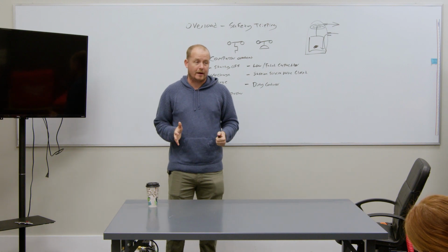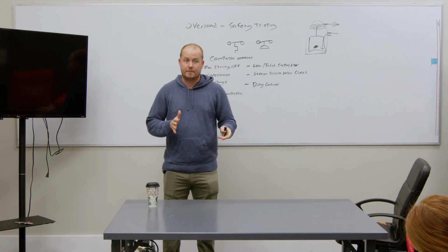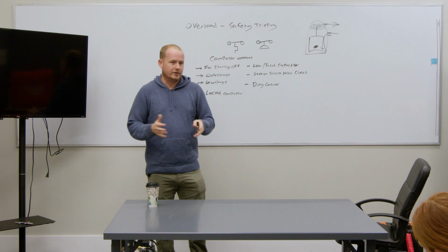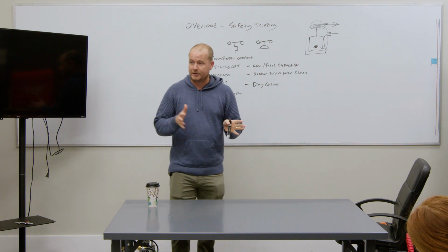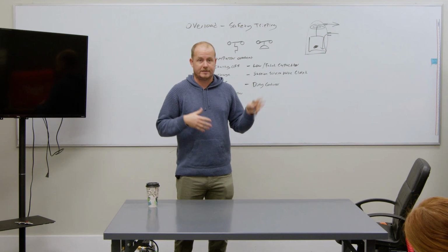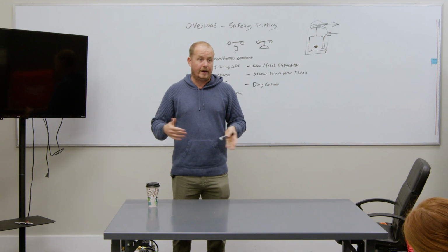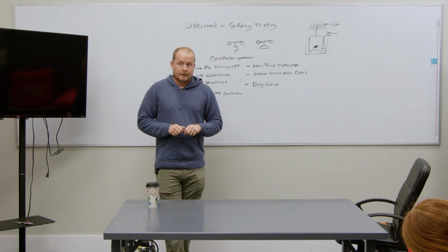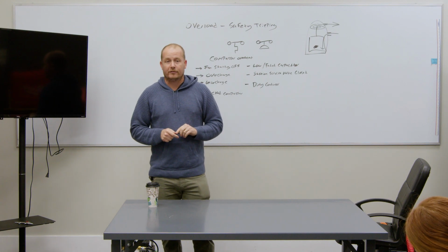So you've got a compressor going on thermal overload. What's going to happen? It's going to be shutting off. If it's locked, it's going to be trying to start and shutting off. If it's running, but it's just overheating because of some of these conditions during running, it's going to run for a while and then it's going to shut off, and then you're going to have to cool it down before it starts again. What is our suggested method of cooling a compressor?